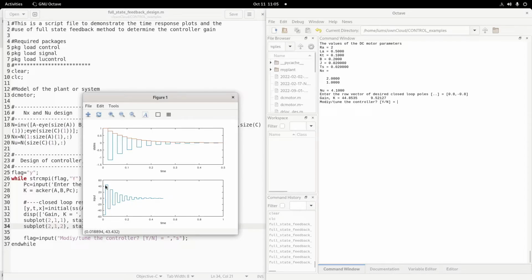As you start moving the closed loop pole placement locations more closer to the unit circle, it will be oscillatory, settling time will be longer, but on the other hand, the control energy will be lower, smaller. So this is the general intuitive feel that you can take away from here. But when you do optimal controls, you have another formal strategy for deciding the location of the desired closed loop poles.